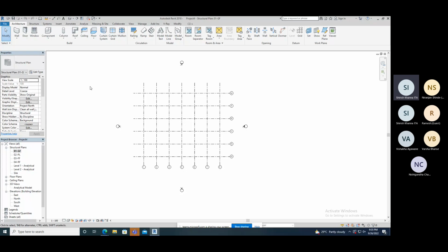You have a floor plan and you are going to the site where it is going to be created. What is the first process? You are measuring all the things. You have one outline, the plot plan. Now, what is the next thing? Foundation directions. We set one datum, or any object, to measure the dimensions and plot the grid.